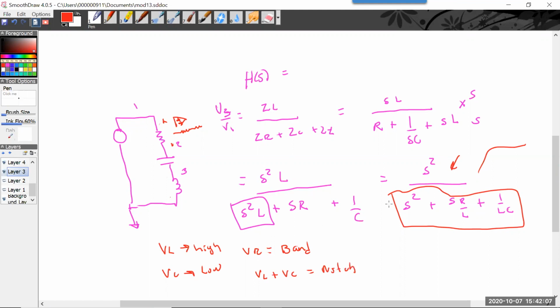Okay. So now I need to design this filter. Really, let's say 50 kilohertz, Butterworth, second order. It's all the same. The R, L, and C values we calculated in the previous example will make this into a high pass filter at 50 kilohertz. And I'm just changing the definition of V out.